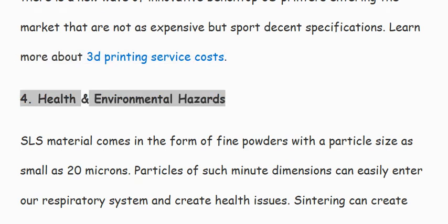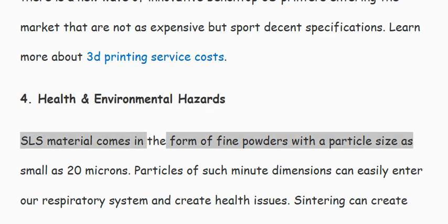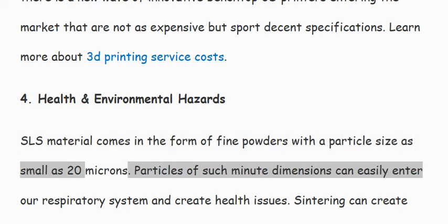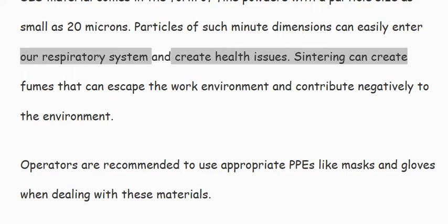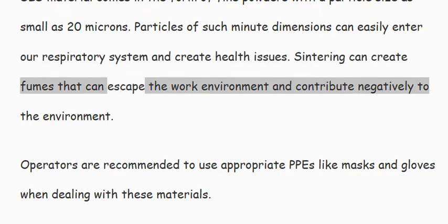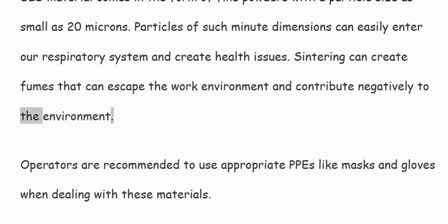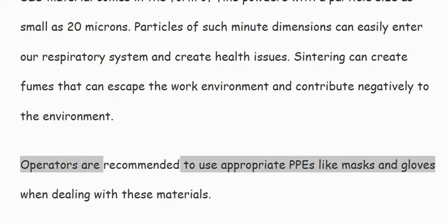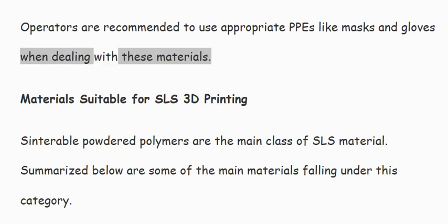4. Health and environmental hazards. SLS material comes in the form of fine powders with a particle size as small as 20 microns. Particles of such minute dimensions can easily enter our respiratory system and create health issues. Sintering can create fumes that can escape the work environment and contribute negatively to the environment. Operators are recommended to use appropriate PPEs like masks and gloves when dealing with these materials.